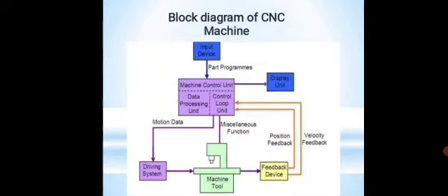Once the system gives a command, it becomes necessary to ensure that the particular function has been completed. This is done by feedback devices. Continuous feedback devices like linear scale, encoder, resolver, etc., are used for position feedback of the motor. Some sensors like proximity switch, limit switch, pressure switch, flow switch and float switch, etc., are used as feedback devices to monitor the different operations.